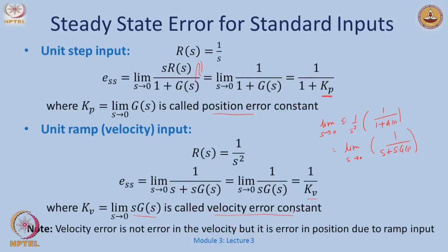So, if I have a feedback loop, I just draw it here again. A reference plus a minus, y of s and so on. If the input or the reference is a step, then there will always be an error. So, the response y of s, if I just take an underdamped, whatever kind of system, and look at the steady state curve, if this is my desired value, my actual value might just be somewhere here. So, this is the steady state error.